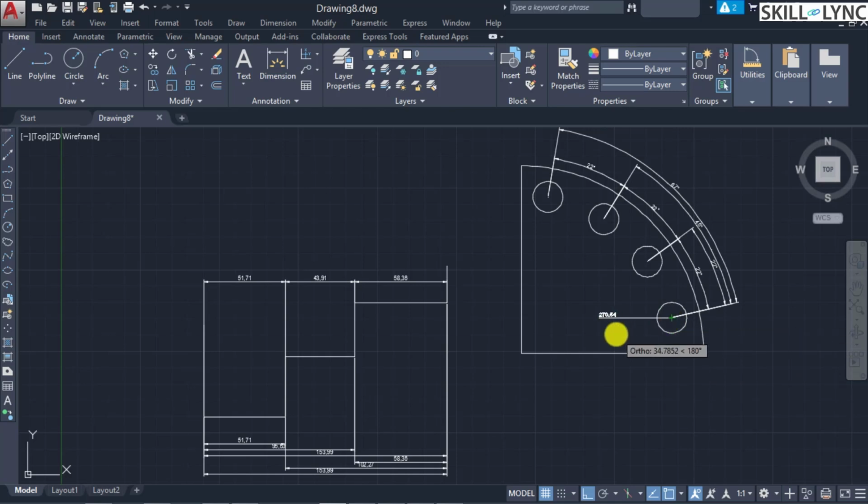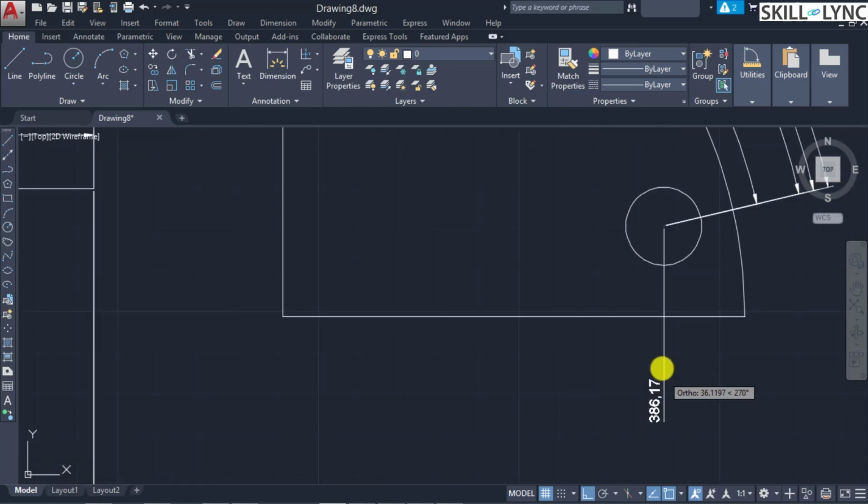this feature point. Once that's done, you can see that based on the movement of your cursor, it changes for the x and y coordinate. So what it means is that this point, 270.54, is the x coordinate distance from the datum plane.